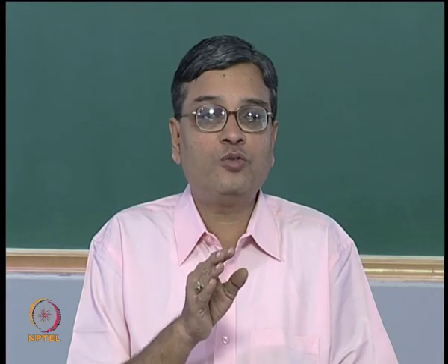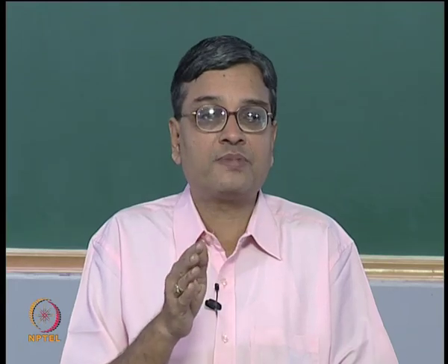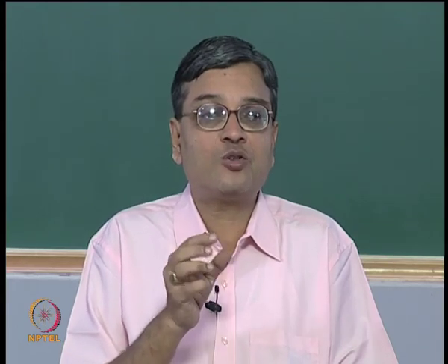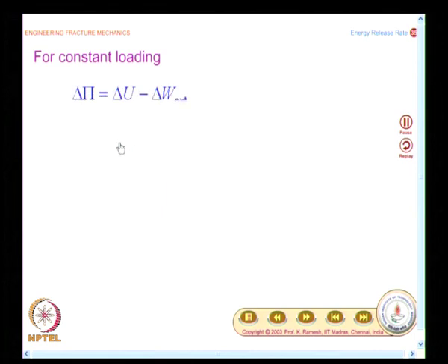We have looked at that from the point of view of potential energy or strain energy. Now, in order to apply the concept of energy release rate to practical problems, Irwin suggested, let us look at compliance. We will get this for constant load as well as constant displacement. Now, let us look at constant loading. Previously, we have come up to minus 1/2 of P dV, this you know.